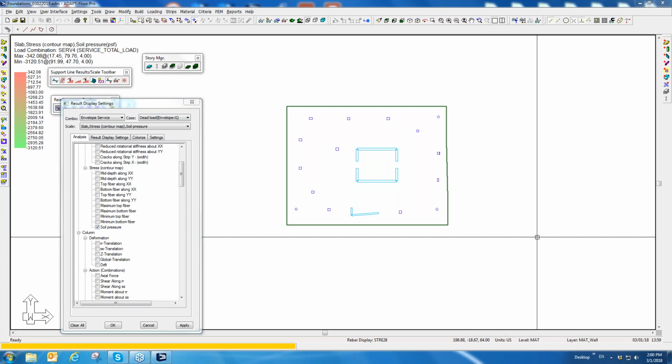You might have a case where you have so much post-tensioning or so much base reinforcement, which is just user-defined rebar, that it's already over-reinforced. So now the program has to add compression rebar to move the neutral axis and maintain the ductility. So there's multiple cases. There's really 6 cases that it might go through. And again, I'll send you detailed information on each one of those. Numerically, it shows you what equations are being used, what material models look like, and what those ratios are.